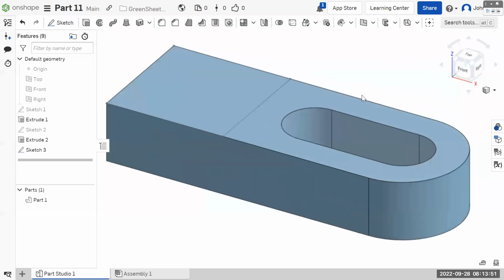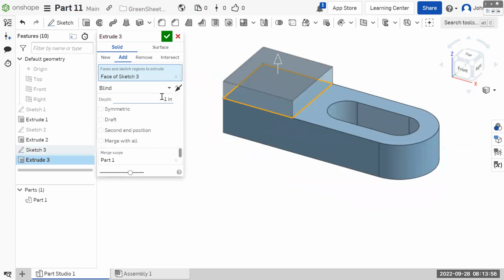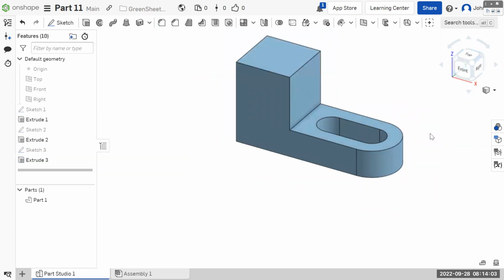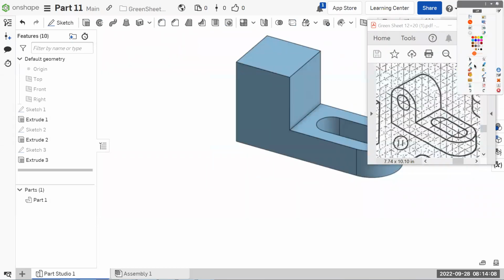Okay, and once we have this, we can then extrude, choose this, and we're extruding this up the total height and then cutting away most of it. Okay, then these two rounded over surfaces, even though it's a solid arc, because of the way the shape is, where it's 4 wide this way and the radius of the arc is 2, we can just do a couple of fillets on this edge and this edge, and it will round it over perfectly.